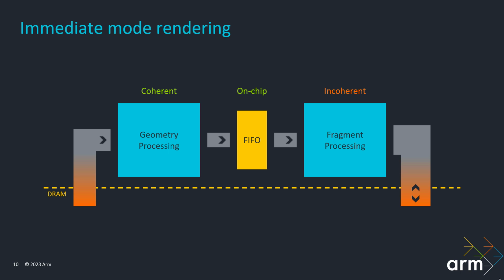This process gives us coherent geometry processing if the application's done a good job and given us a good index buffer. The data access is local and we get good memory access patterns, and the output stays on chip, so the bandwidth for the vertex shader outputs is very efficient. The downside of this architecture is that we are processing triangles coming out of that FIFO in application specified order, and applications generally do front to back sorting, not spatial sorting.